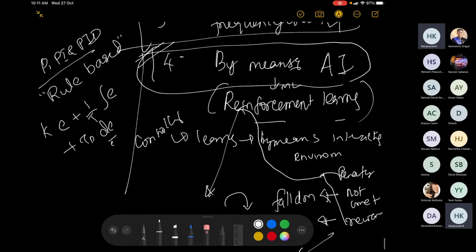So this is a rule, right? It contains 3 components. The first component gives you some proportional push. The second gives you some integral action to take off the offset, and the third gives you some anticipatory action. So this is rule based, and this rule is fixed a priori. And this rule is based on your assumption that adding these components might help you to control.